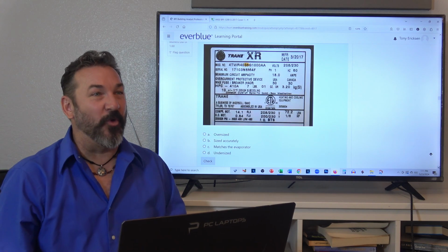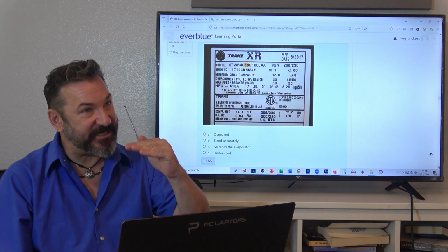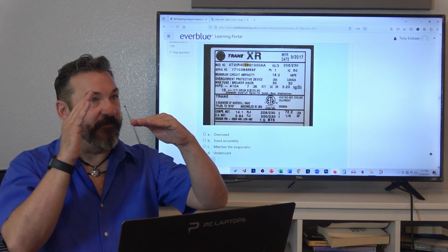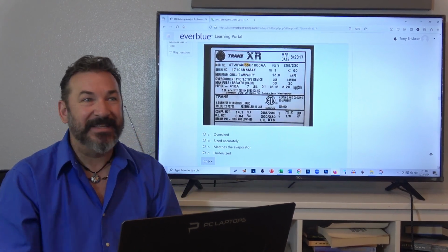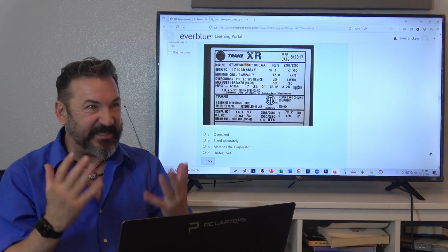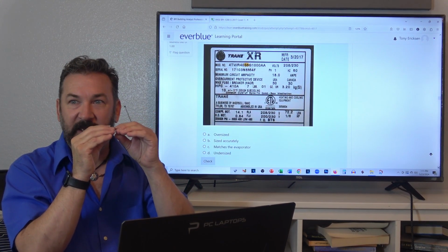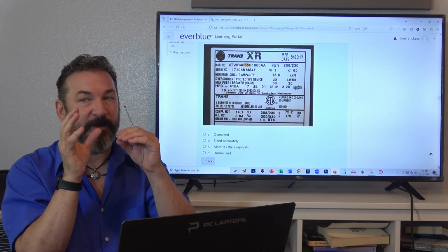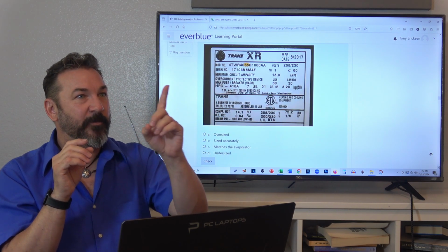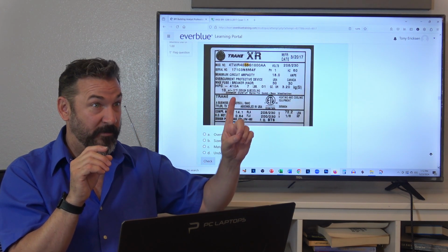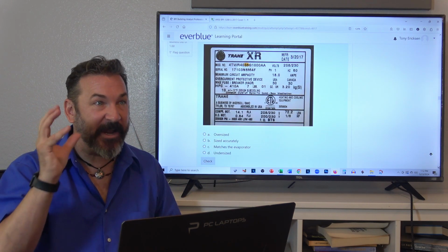So we're going to go one step more. How many BTUs does it take to change the state from water to vapor? You're at 212 to go to 213 of steam. It takes 970 BTUs to change it from 212 degree water to steam. That's a boatload of energy, because every degree before that took 1 BTU per pound, but that last pound to change state into steam took 970.